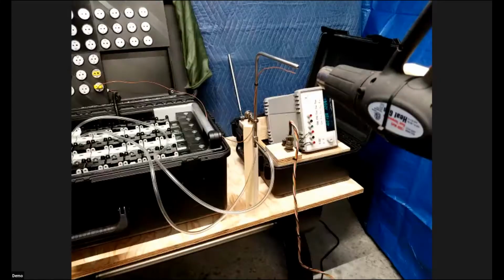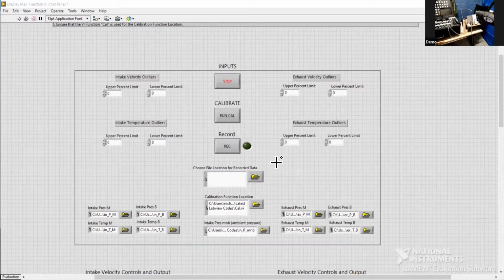So now, if you hear us, now that I'm speaking, you should be able to hear us and see the demo set up there, showing the heat gun and then the pitot-static tube. And then this is the thermocouple that'll be testing the heat. So when I turn this on, it's going to be blowing hot air right here at the pitot-static tube, detecting that air pressure. And then this thermocouple here will be picking up that heat. So we're going to do it on low first, and then kick it up.